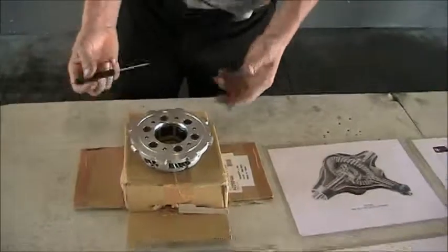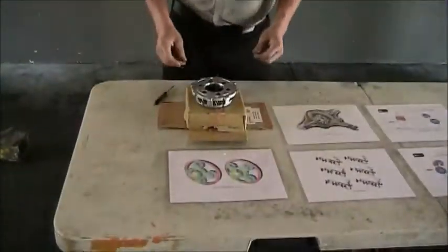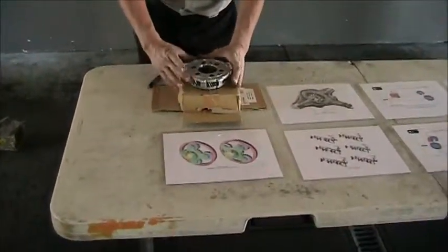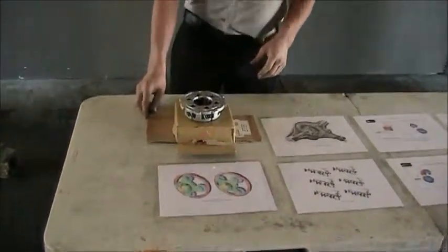An automatic transmission can have 2 to 4 of these inside of it, depending on the number of gears it has. And then it has bands which can apply and hold the outer sections, or the sun, or the ring gear, as well as clutch packs, which would be attached through a drum to hold the planetary gears. So again, it's all activated hydraulically, and they're very complicated. It would be difficult to explain that to those people on a video, so we're going to keep it simple in here. Now we're going to walk over.